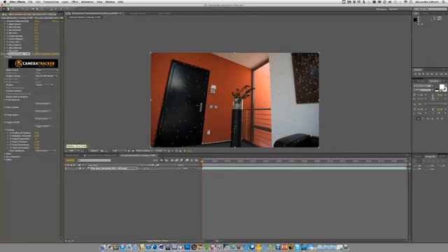We're going to display our tracks, but I just don't want to have the viewer updated by our tracking progress, so I just hit that off. And the advantage of hitting that off is that we don't have to switch off our autosave. After Effects camera tracker will not be disrupted by any After Effects events, so that's quite handy and gives you the same result in the end.